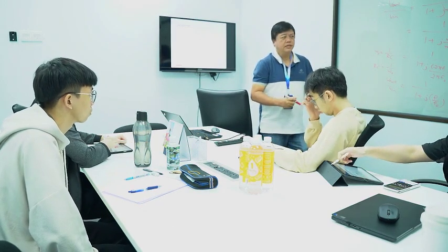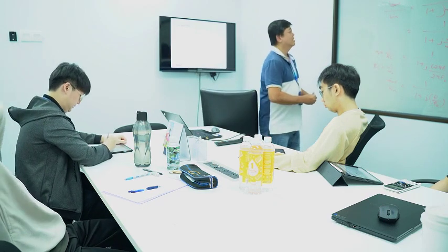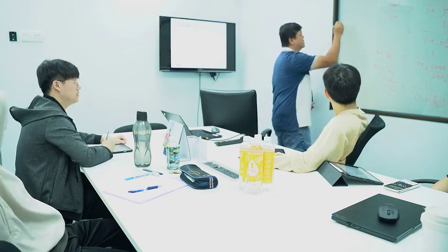So now you have your j. You understand, to get this formula you have a j here. Actually, I want to prove how to get the minus 3 dB. So f is your input frequency, f0 your cutoff frequency. So what you need to do when you have j to find the value? You remember how to find the magnitude of a complex number? You need the modulus, remember? So you do the modulus.